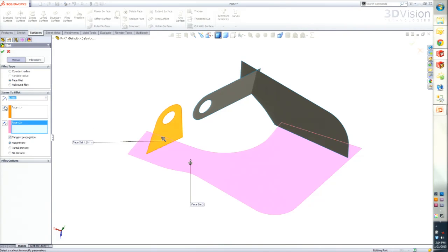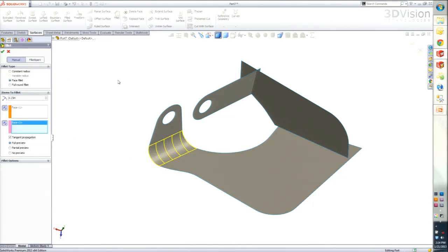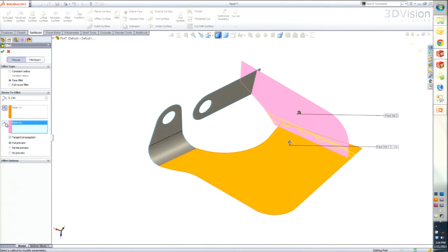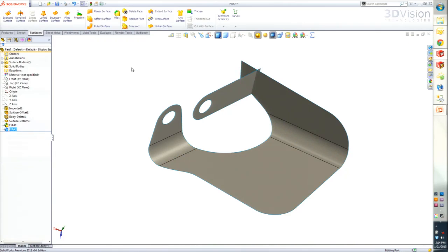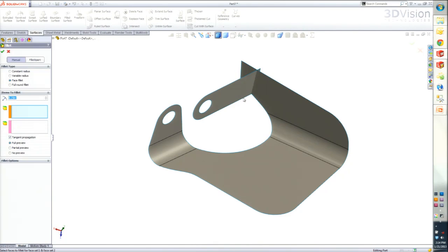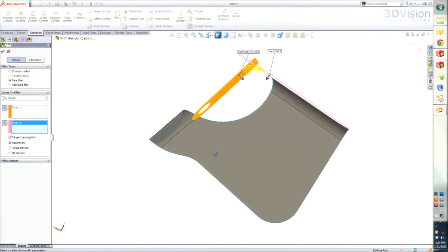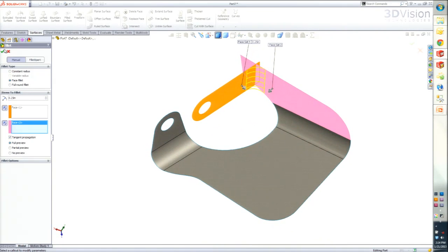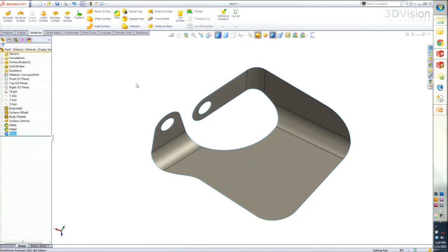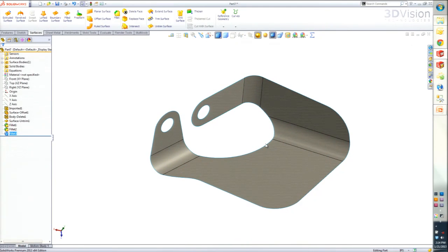But the benefit is we have more flexibility in how SolidWorks is going to calculate this. So I'm going to bump this radius up to 2.5, and as long as it's big enough to bridge between that gap, we can go ahead and fillet that. So, pretty powerful tool. And you just need to make sure that those two arrows are pointing in the right direction as well. And even if the surfaces are intersecting and overlapping, it will go ahead and act as a trim tool as well. Okay? So now I've got this.